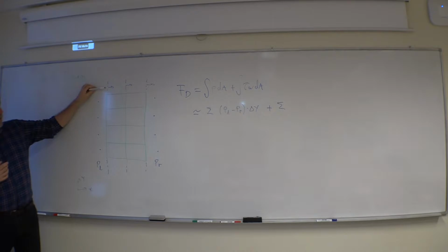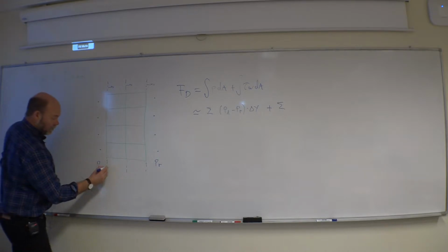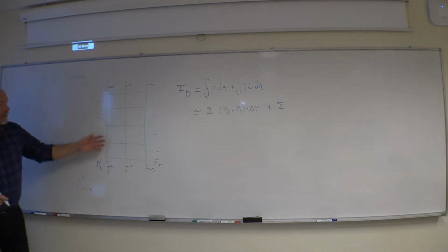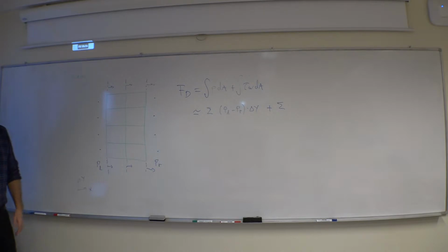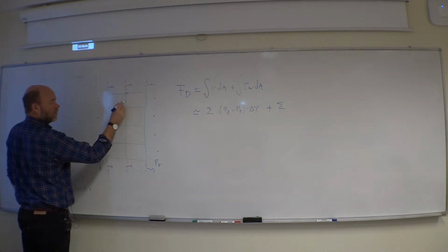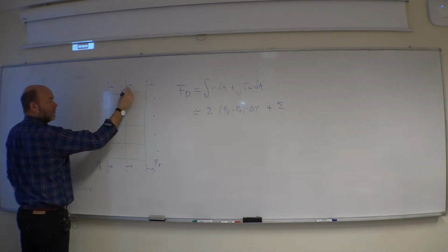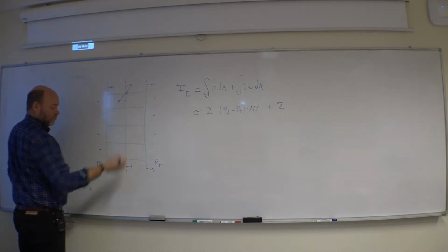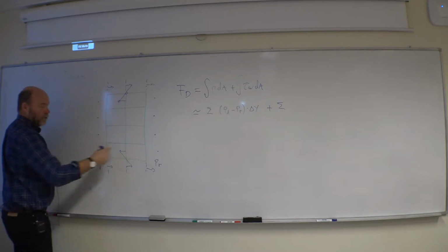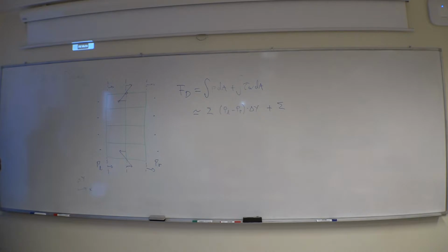On the center we have the location of our streamwise velocity. Same goes down here. Inside I use boundary conditions, so I get 0 velocity here on the wall. So I construct a velocity here so that on average we find 0. The corners I have to treat specially, so don't mind that.